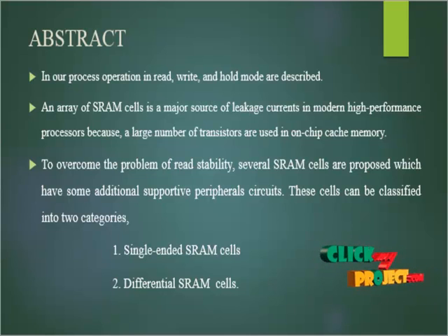The rest of the paper organizes the structure of the operations and the SRAM cell structure, with the read, write and hold modes described. In the simulation, for low power applications, variation of supply voltage decreases dynamic power and the first order leakage power, and the supply voltage is lowered below the threshold voltage.